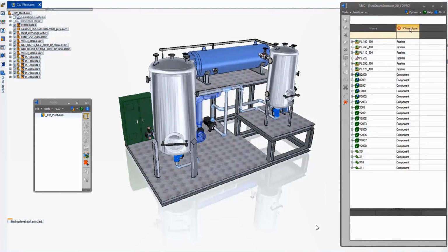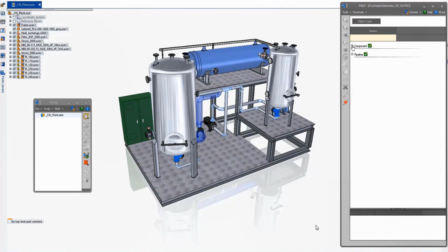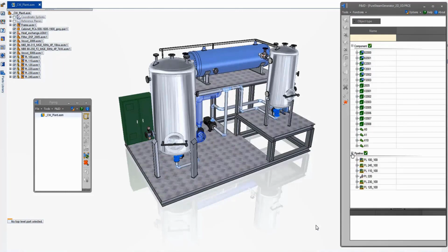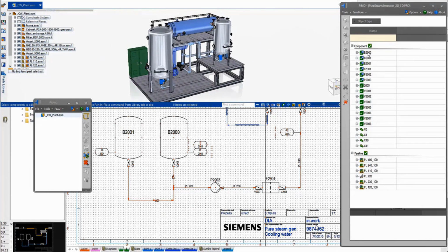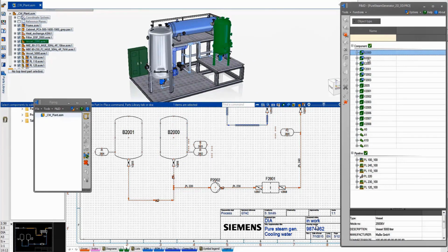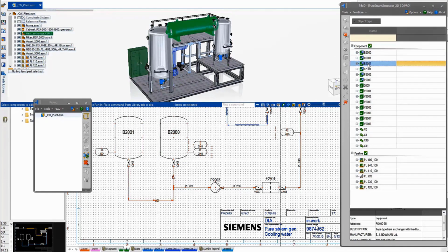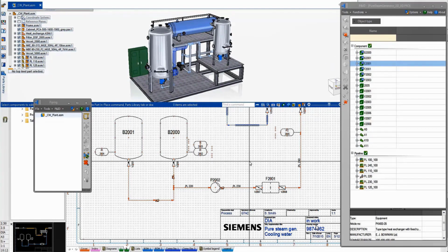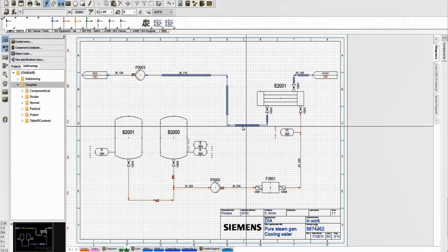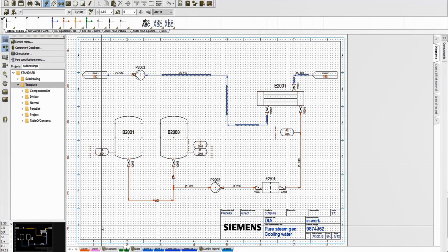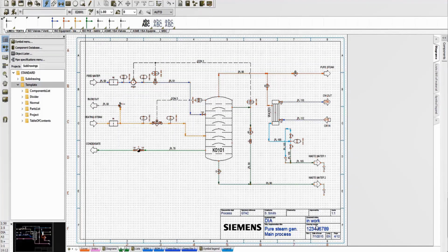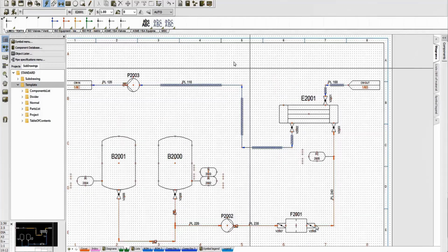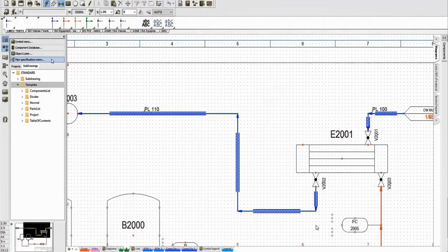The to-do list is configurable. For example, changed from a single list of components or filtered by component type, making it easier to find the things you're looking for. More importantly, it supports cross-highlighting in both environments. Selecting an object will highlight in both the 3D model and the 2D P&ID, as we see here. For now, let's focus on the 2D P&ID schematic of our piping system. A nice feature of Solid Edge P&ID is the built-in report capability, so it's easy to keep up with all the information such as component lists and diagrams.